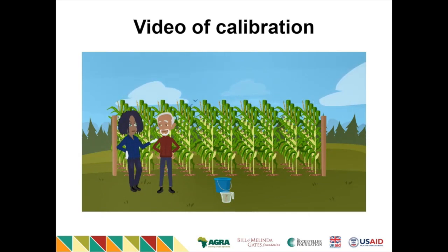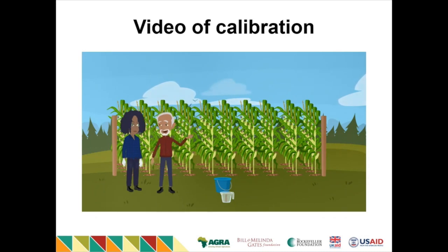There are a few ways to apply a greater volume of water per hectare. You could either walk slower. If you walked at half the speed, you'd be applying 422 liters per hectare. Or you can use the same type of nozzle from the same manufacturer. There will be nozzles that will deliver twice the volume. Perfect. Let's get to work then.